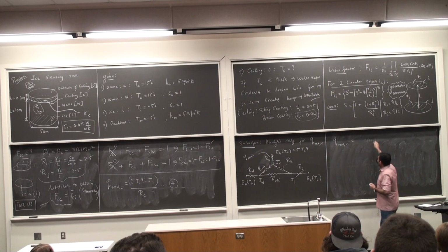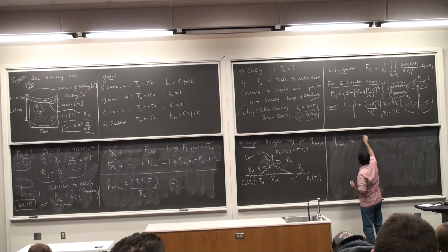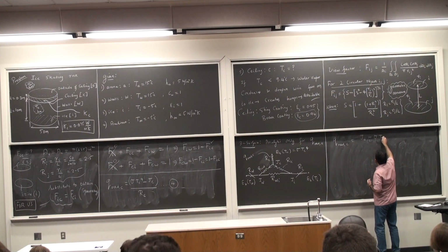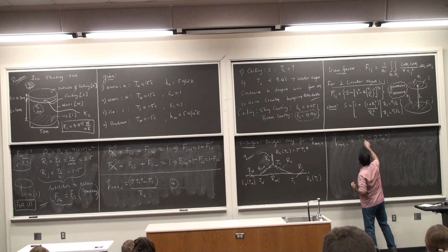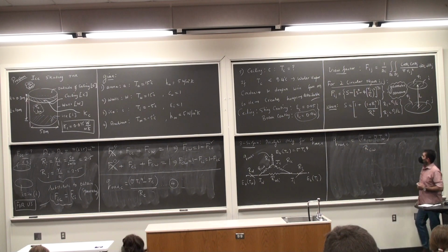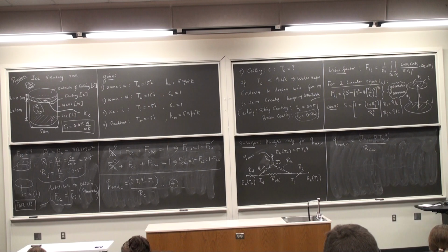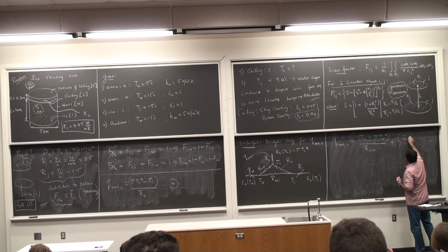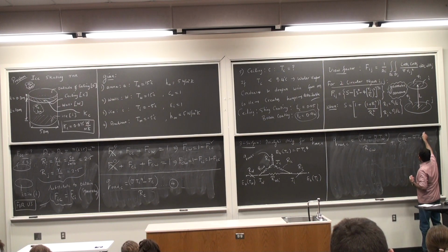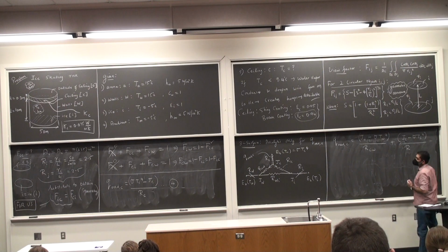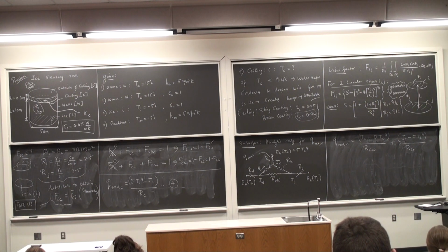So if I do that, this is going to be Jc minus sigma T wall to the power 4 by RCW, which is known to us. T wall is known to us. Jc is not known to us. Plus Jc minus sigma Ti to the power 4 by RIC. This is equation 4.